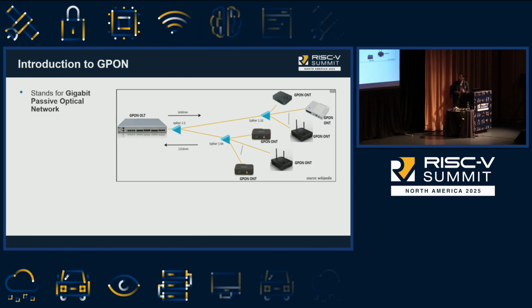So basically, if you see the diagram, it consists of an OLT box called the Optical Line Terminal, and then there are endpoints, the optical network units or the optical network terminals. This technology is based on the ITU-T G.984 standards. It's fiber optics. On the left side, you will have the Ethernet connecting to the OLT, and then you will have splitters in between, and the signals are multiplied to multiple ONUs: 8, 16, 32, 64, and it goes on.